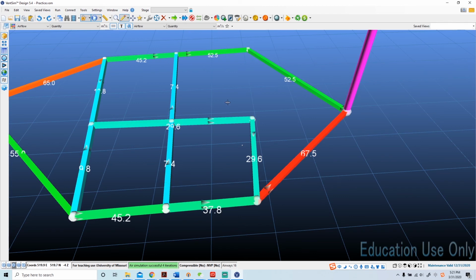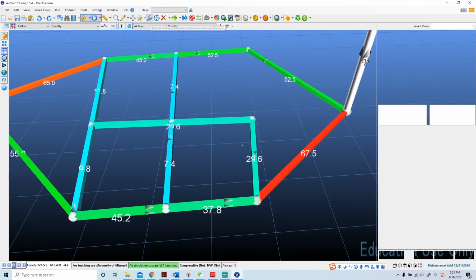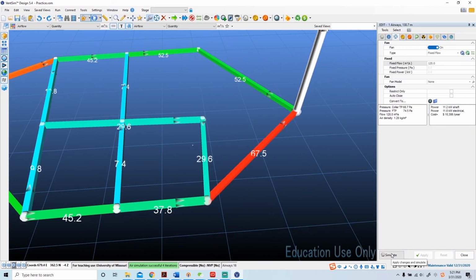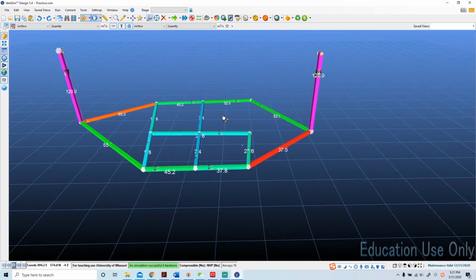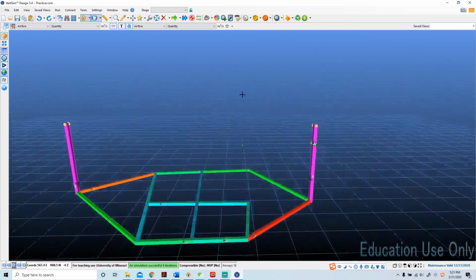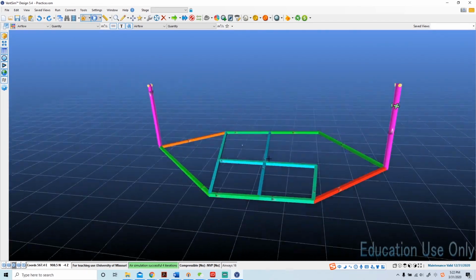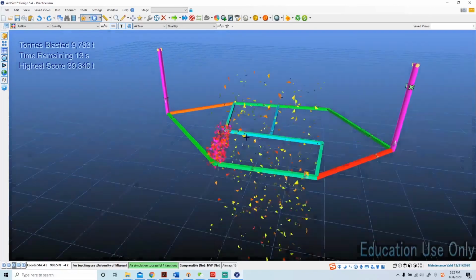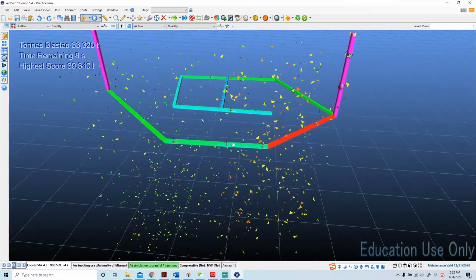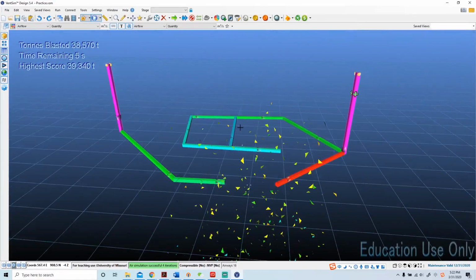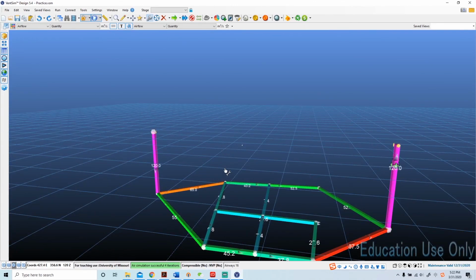Anytime you have made changes, make sure you rerun the simulation by clicking the simulation button in the edit window or the icon here. Lastly, if you are bored working on the model, right-click the mouse, select Flight. You can shoot the airways that you have built. Press the ESC key on the keyboard to escape from the flight mode.